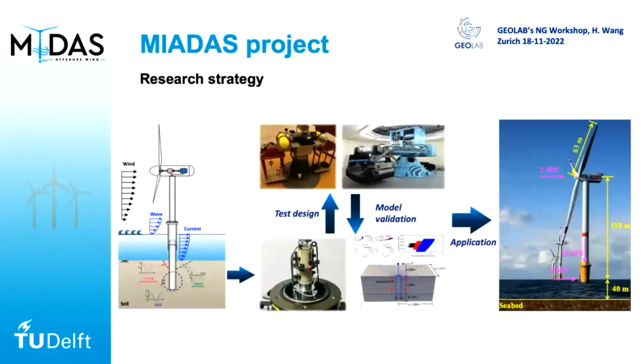And here you can see basically an idea of how we are really going to do this project. So we use the element tests to understand the soil behavior under long-term multi-cycle loading. And we have already developed a soil constitutive model to simulate the long-term behavior of the soil element. And at TU Delft, it's quite unique that we have a small centrifuge, but also with a 10 minute walk at the Terrace, we also have a huge centrifuge. I will show you later. And in the end, we are going to develop a new design model for offshore wind monopiles.